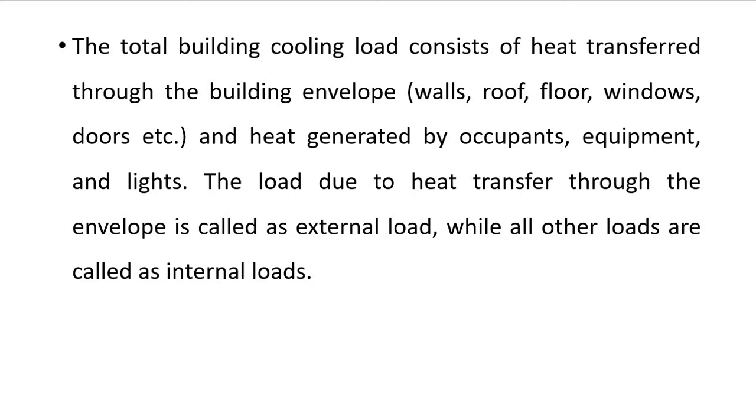So there may be heat leakage from the outside to the inside. The total building cooling load consists of heat transferred through the building envelope. That heat will transfer through the walls, roof, floor, windows, doors, etc.